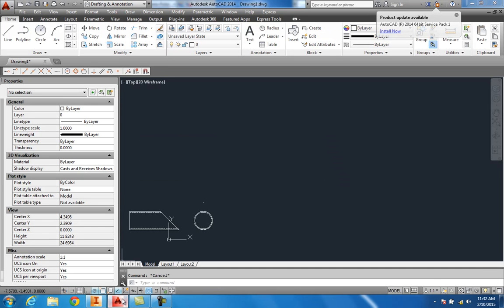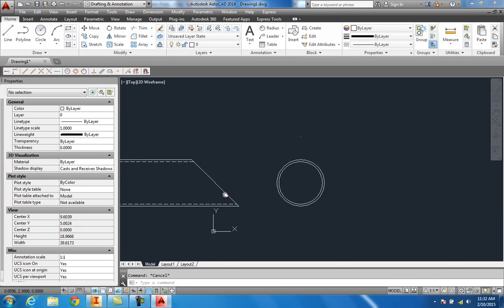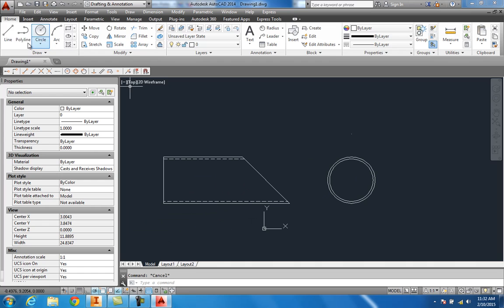Now, to make the top view in AutoCAD, let's go ahead and project everything out. I'll bring this up here and I'll make my miter lines. Looks pretty good, and I'll bring that across. And I want to shoot this 45-degree miter line up here.